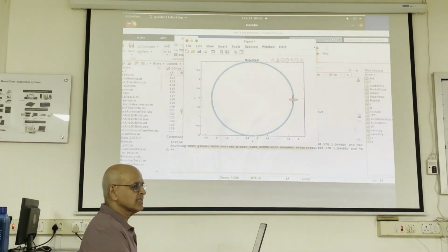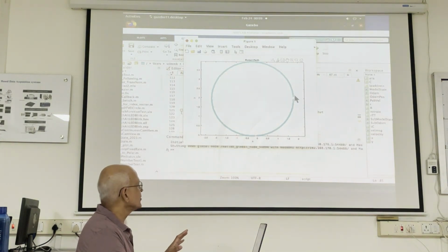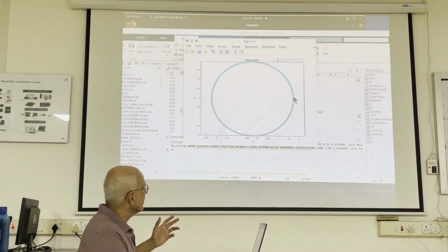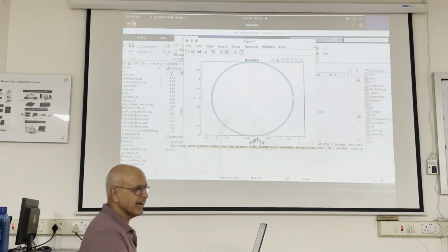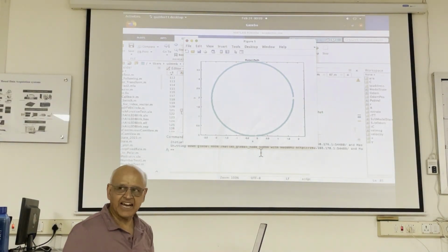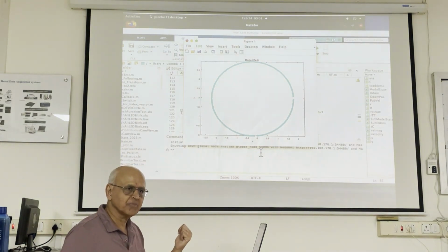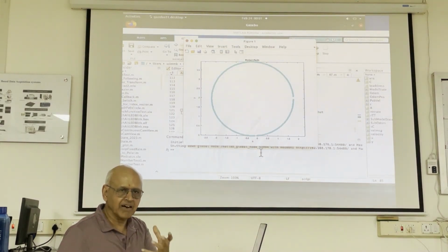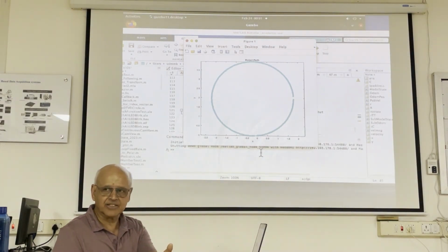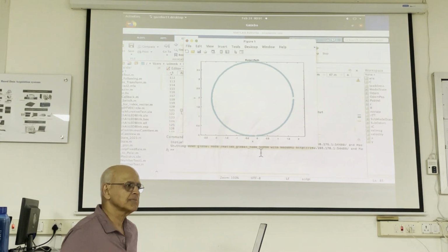Now that's just a glitch. Okay. If I do it again, you see that it fills out that. Over here, see, it stopped a little bit short. Can you see that? It's because we are measuring time. We're not measuring distance. And this is what happens when you have an open loop control system. You will not be able to close or get the target you want, because then you should be monitoring the variable you want, right? We are monitoring time in order to get to distance. That makes it an open loop system.